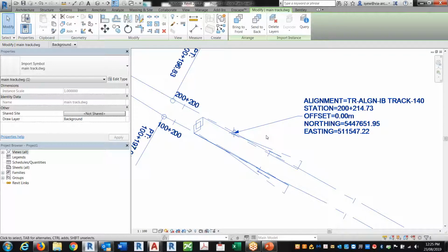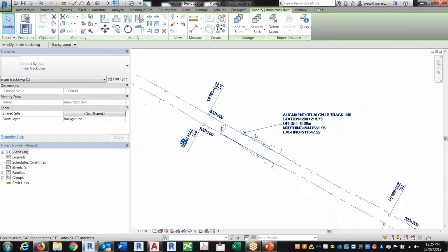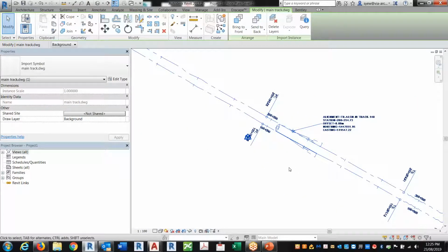So what I did is that every time I receive files from a consultant, I always take the origin point from the old file, do a circle, and then copy it and paste it into the new one just to see where the origin point is. Okay, so that next time if this origin point got moved, at least that circle designates what has to be your origin point. So you copy and paste your origin point from the previous file to the new file. That's correct. You have to do that, right? Because if you don't do that, this is where everything will break.